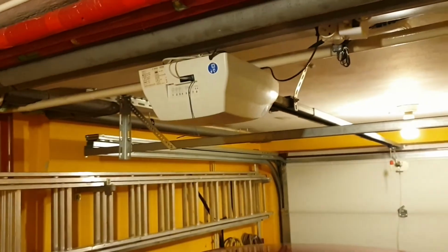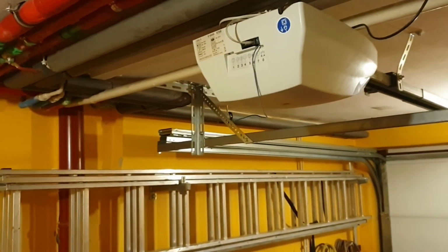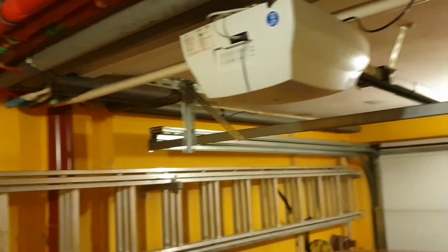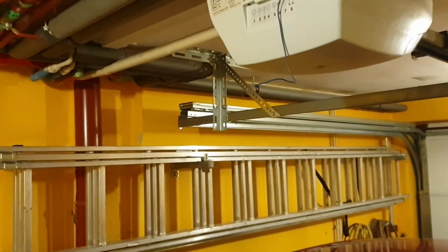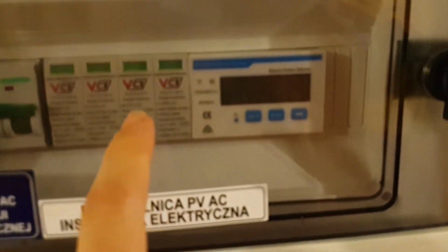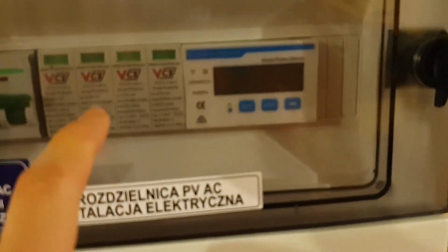So you have those panels and those two strings are connected using 4 cables and also a fifth for ground through my chimney. It was the easiest solution and all that is connected to that box you can see here, and I have also 2 surge protectors. So those are responsible for protecting the DC voltage on the input of the inverter, and of course you have also the AC surge protector at the output of the inverter.